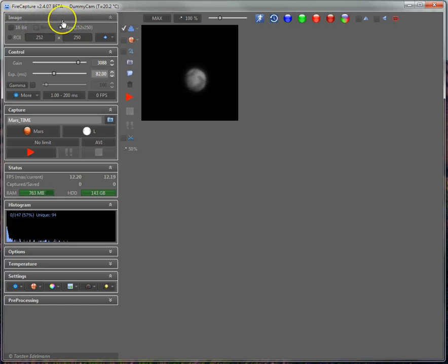The topmost is image. There we can control the camera video mode, and it's 16-bit video mode, or you can change the image size read out from the camera. That is controlled here with that button over here. ROI just means the region of interest. That simply means reading out a portion of the camera sensor. So you can either pick max or you can change ROI, and you can pick any image size you'd like